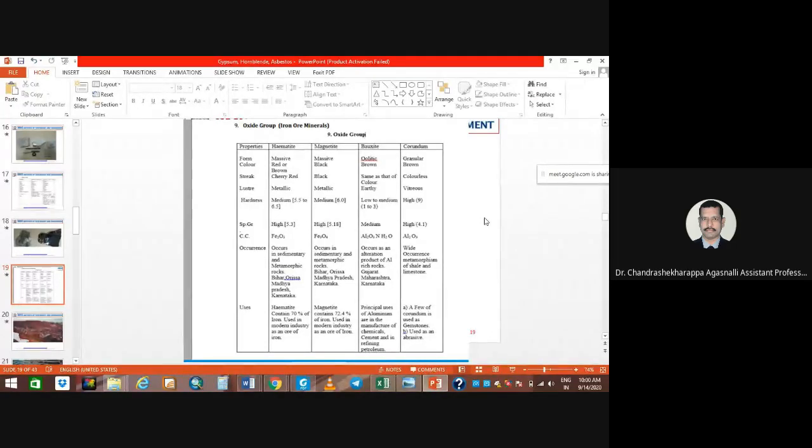Then we will do the analysis: strength of the rocks, rock quality designations, whether it is a hard rock, medium rock, or highly weathered rock, and also the chemistry, whether there is gold, copper, lead, zinc, iron ore. All those things we will assess from the drilling core, which we recovered from the borehole.